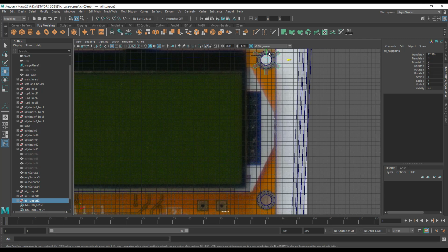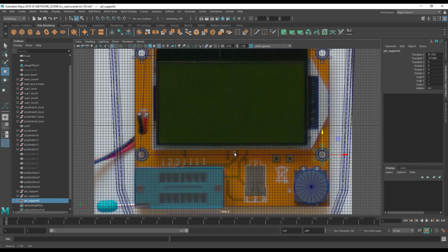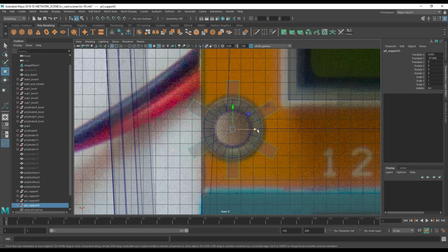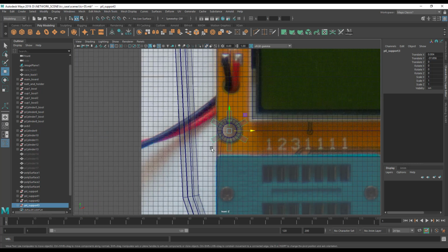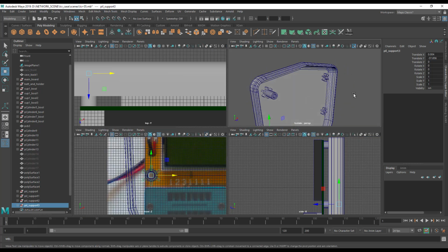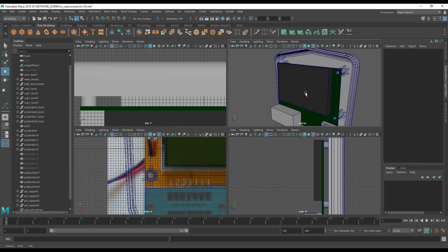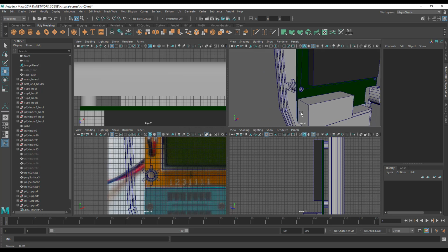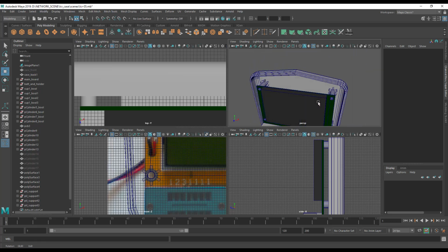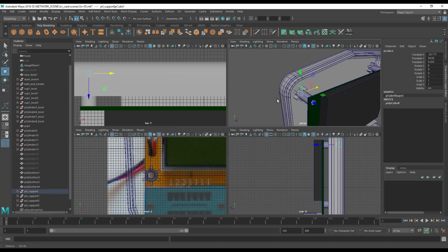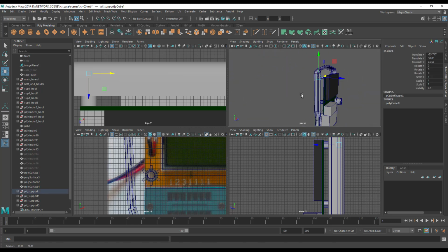Control D, and again just come down here and do the little support thing. Control D, come down here and do the little support thing. You might want to take a bit more time and effort getting a bit more accurate, but that's perfectly acceptable for me. And now if we hit Control and 1, you should see you've got your pillars with the supports round. They're not interfering with anything else. We got plenty of room for it, so why not? You could even make them, if you wanted to, a bit higher. I think this is going to be enough in my case.